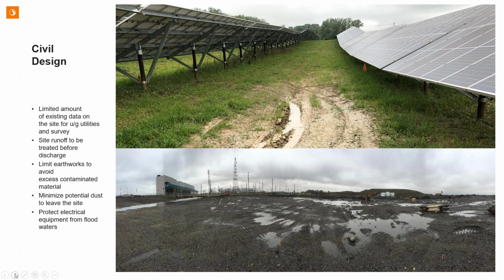So getting into the civil design, some of the items that you need to consider. There's a limited amount of existing data on the site for the underground utilities and survey. So you need to be aware of what may or may not be buried below grade. The site runoff is required to be treated before it can be discharged. Your earthworks are limited due to the contaminated material on the sites. As previously discussed by one of the other presenters, there's potential for dust, so you need to minimize the dust that leaves the site. And you also need to protect your electrical equipment from floodwaters.